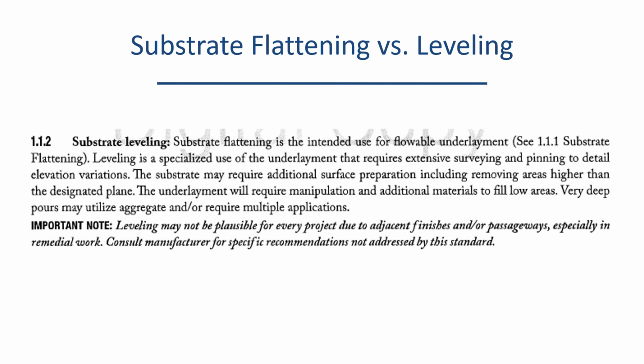If we have to go in and level a large area, and we do it all the time, truckloads of material, you really have to be very, very cautious in what you're doing. You have to know your area, the floor, where it's out, where it's in. You have to pin it. Commonly, you have to do extensive surveying, in other words, to know where the low spots are, the high spots, so you can easily identify those as you're pouring the leveler.